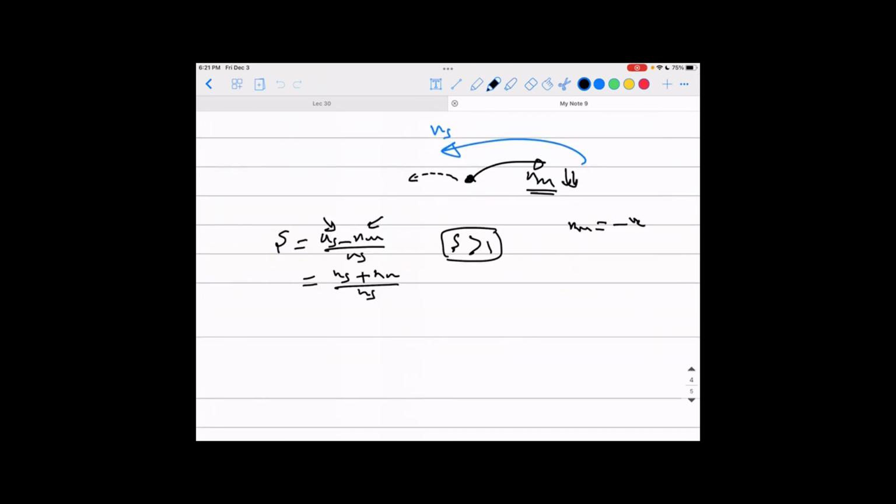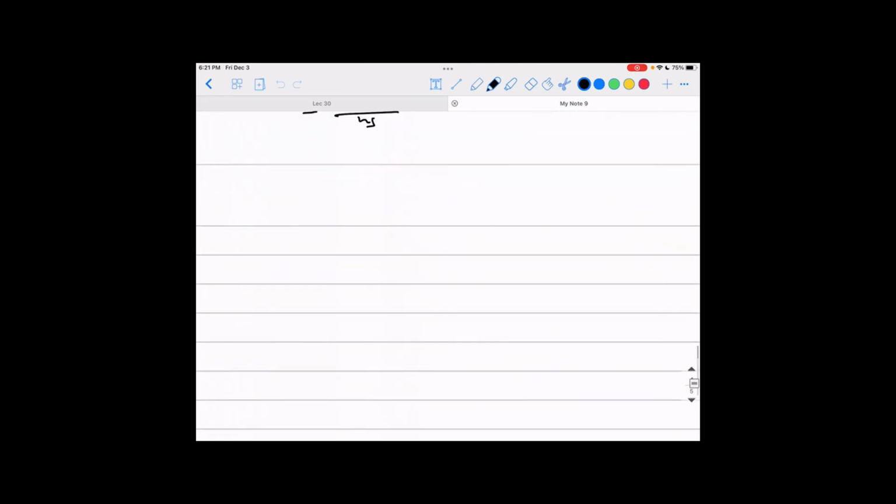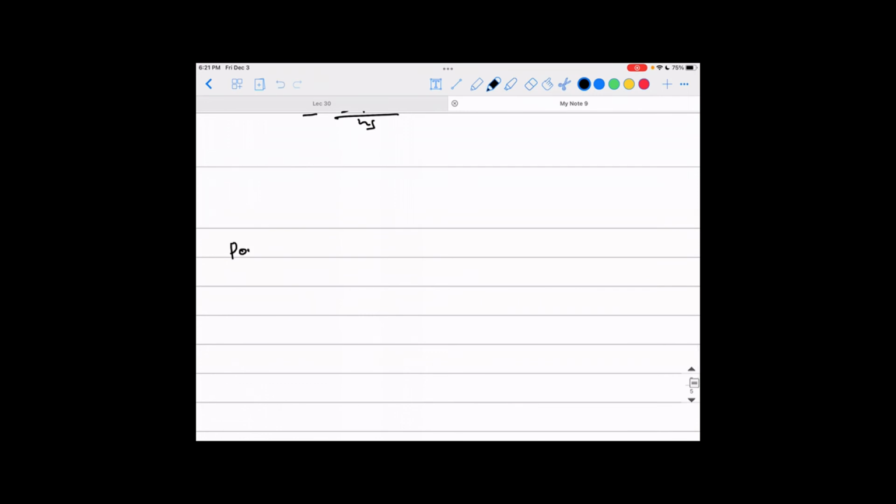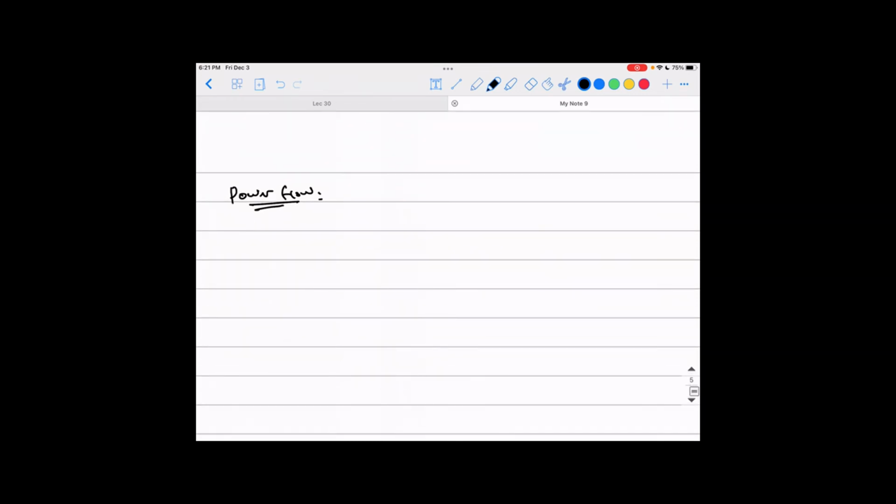So for this mode, it's not a motor, it's not a generator. It's a totally different mode. That's why it's the third mode of operation for a three-phase induction machine. Okay? If you look at the power flow diagram for the plugging mode, what happens is that you have electric power, P electric, coming from the stator supply.